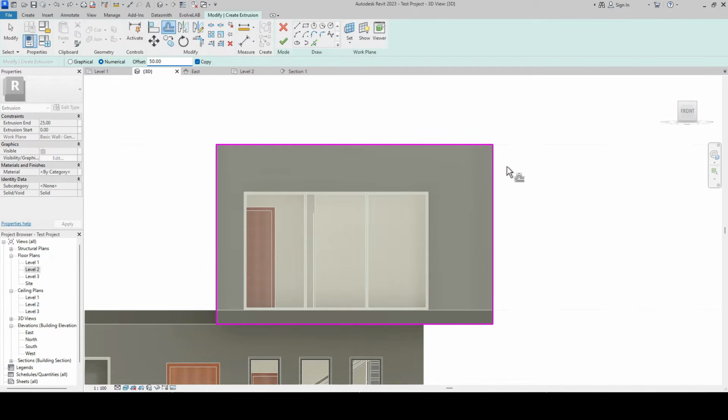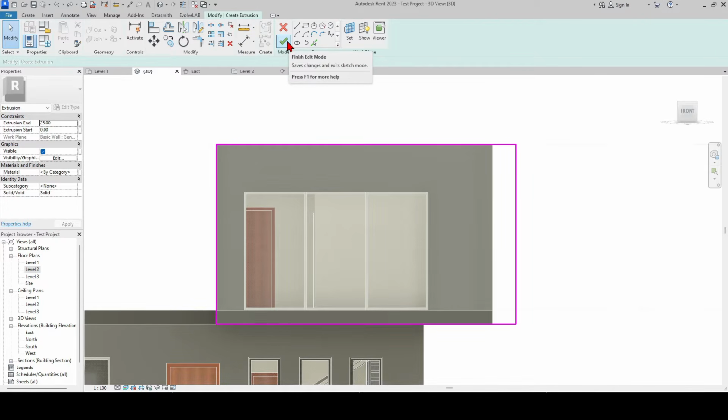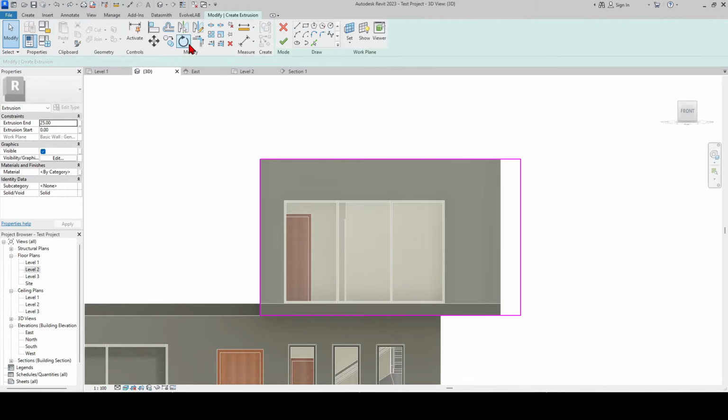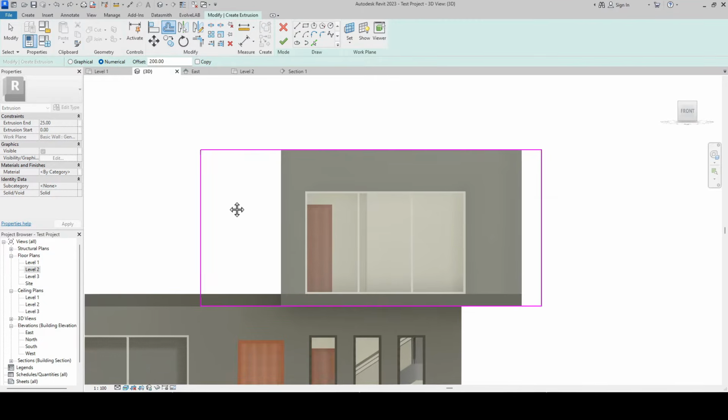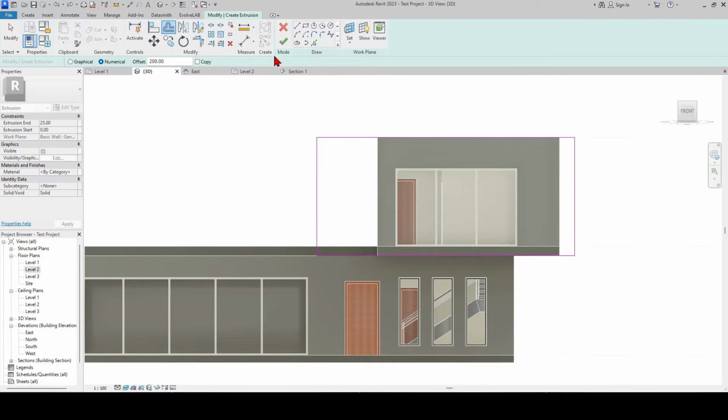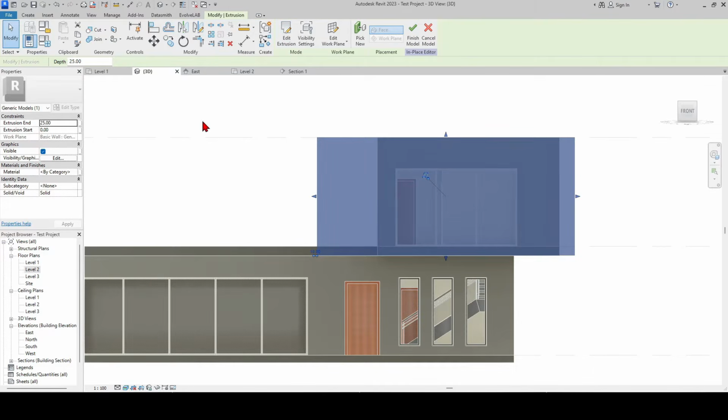Since we want this line to be moved in this situation, we close the Copy tab and then we just click. If the Copy tab were open, it would have copied another one of the same line at the specified distance, as you can see. Let's offset this part by 200 centimeters as well. Once confirmed, our mesh is created.